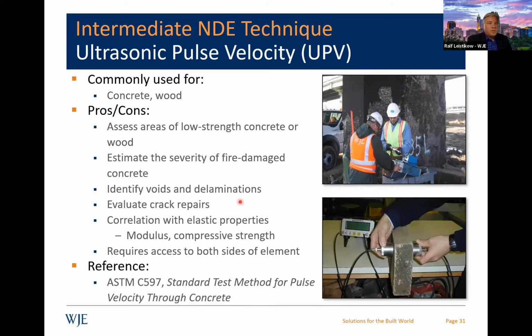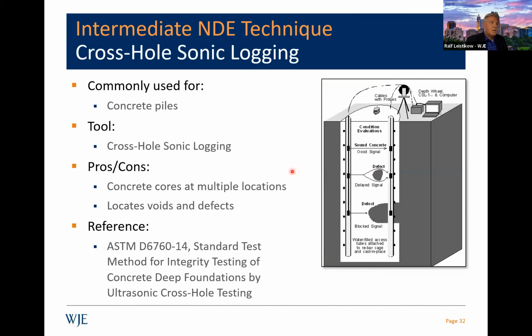You can identify voids and delaminations in concrete. You can also evaluate crack repairs, whether they have been fully epoxied, for example, something you're injecting and trying to figure out if it's been fully filled. You can also, with some correlation work, determine elastic properties such as the modulus and compressive strength. That can be done, and obviously you need a more advanced user. And again, both sides have to be accessible to do this. So for some applications, this may not be the right technology.